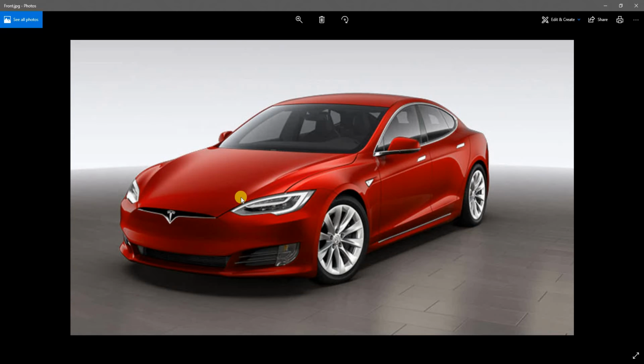So looking at this photo, on the Model S's front hood, there is this kind of sharp edge running along like where my mouse cursor is, and also another one here. So they would be good edges for the surfaces we're creating in SolidWorks, because if you've got a sharp edge or a kink in a surface, you want to make that your boundary, because it will be hard to capture that detail if it were in the center of a surface you're modeling.